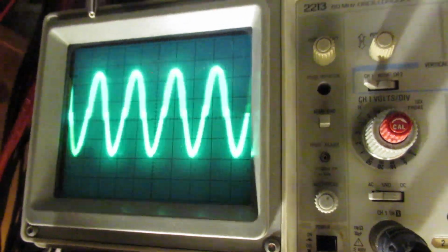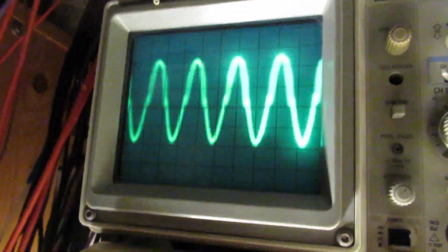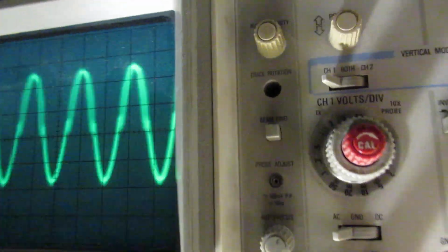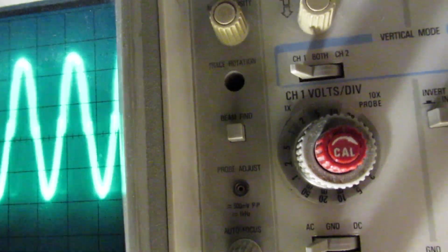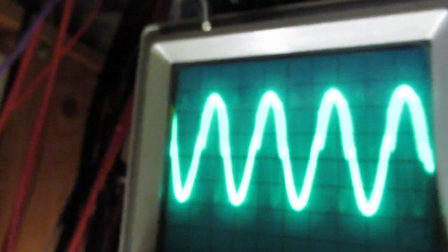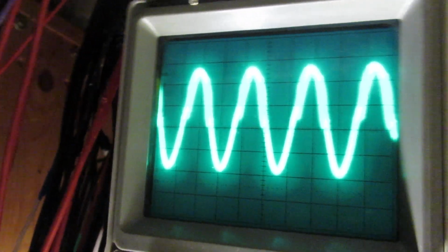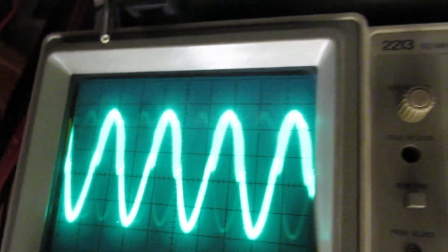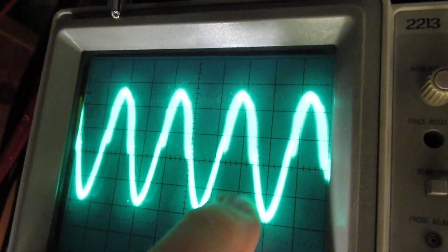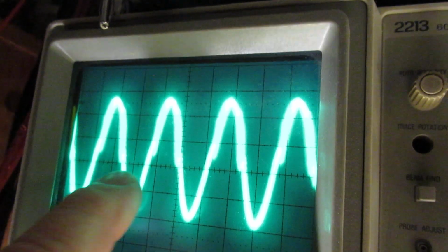And of course there's also a difference when we go to other frequencies. Let me go to a very clear situation. This is 400 Hertz, and now we are on 4000 Hertz. Let's see. Again, we have different problems, by the way. Here there's a broadening in the wave. Here there is crossover distortion.